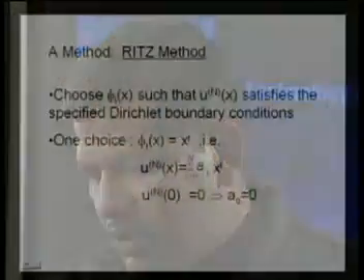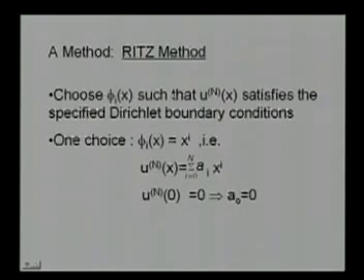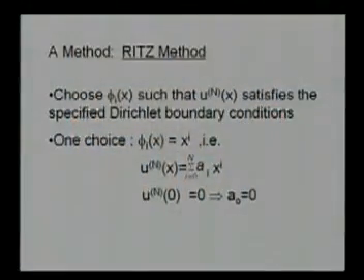So in the next class we are going to develop the Ritz method for the model problem that we have taken, where the n term series that we are going to use for the approximation of u of x will be given in terms of very specific functions. We have said that we would like our delta un as well as un to satisfy the 0 condition at x equal to 0. So let us take these phi i's to be functions which are x to the power of i, that is x to the power of 0 which is 1, x to the power 1 which is x, x squared, x cubed, and so on up to x to the power of n. Then un of x is a summation of ai x to the power of i.